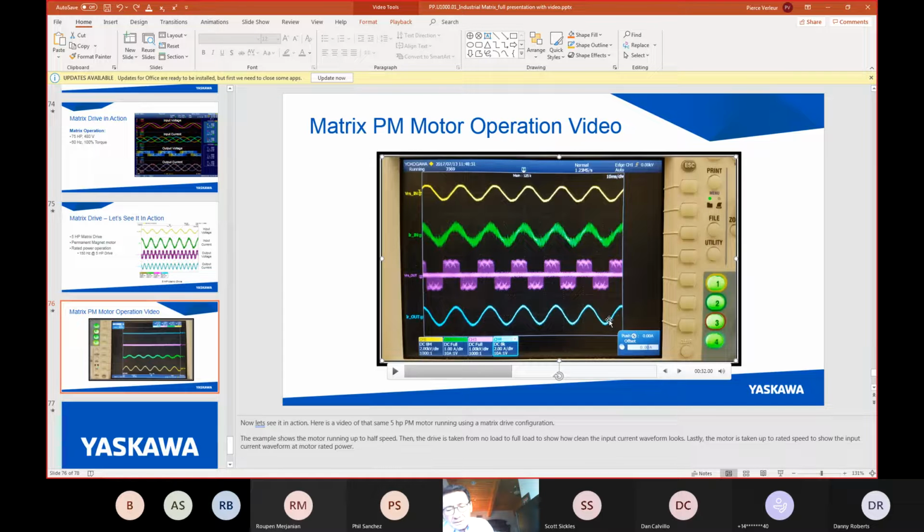And on the output, he's got an AC reactor or even a sine wave filter to protect his downhole submersible pump motor or his big turbine pump motor. This is something he's done for the last 15 years. The specification is written around it. And it's a pretty significant sales challenge to change that. You do it one step at a time, as the old saying goes.